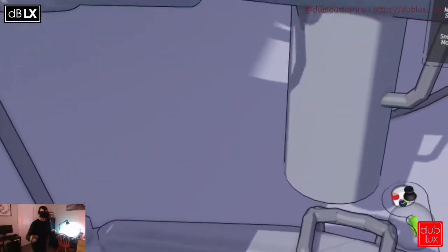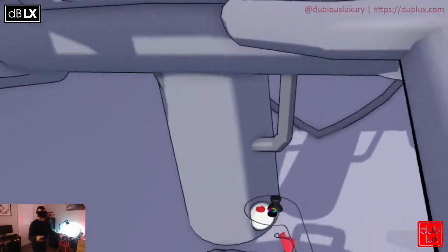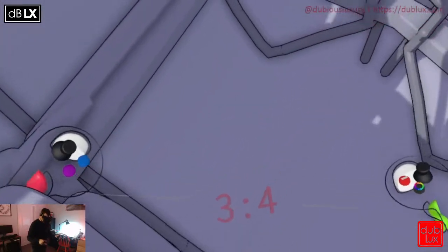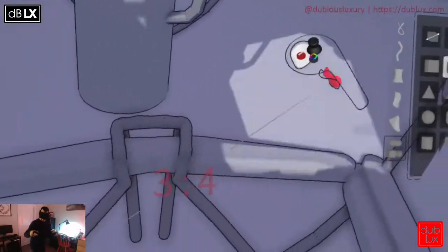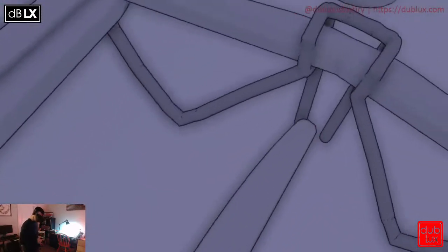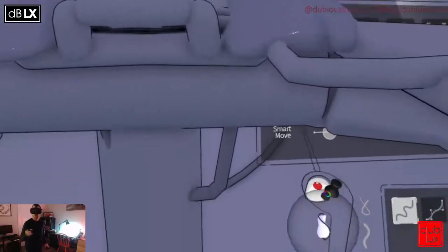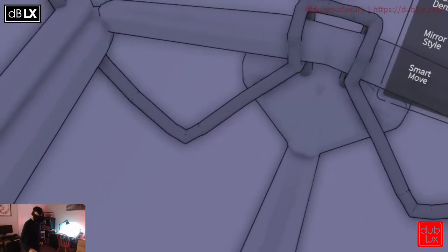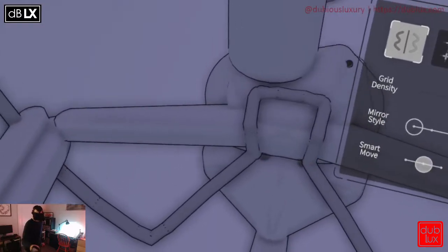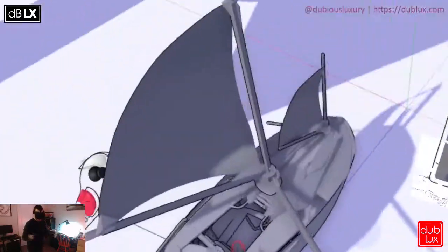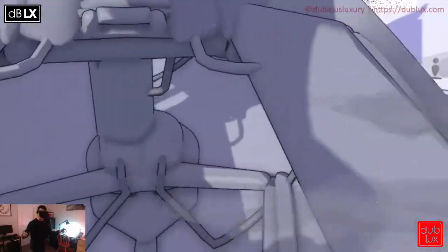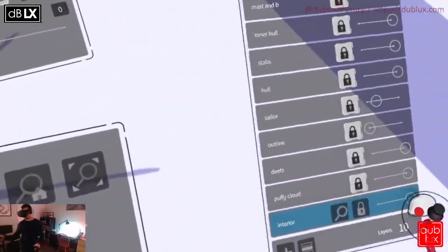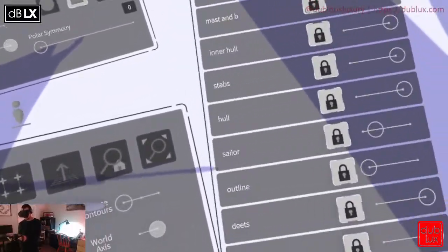Okay. And then once we're in, I don't really care what happens down at the bottom, but I will put a structural support, another volume here along the keel, and I will mirror it so that we're sure that we have good symmetry. All right, cool. Good enough for me. Let's work on our decking. So I don't think we have a layer called deck yet.